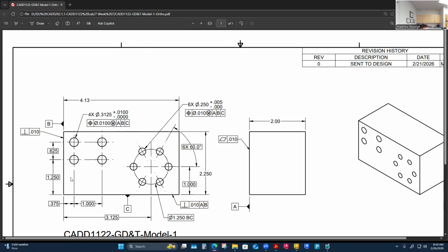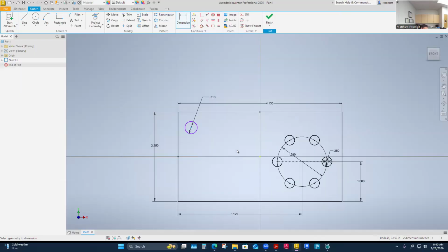Looks like to me, I'll probably move this hole into this position here and just go up 1 1/4 and over 3/8, 0.375. So up 1 1/4, over 0.375. I'll place this hole. 1 1/4, 0.375. So from here to here, it's going to be 1 1/4, and over 3/8.